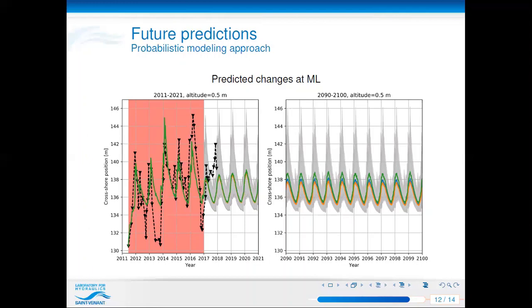so meters of variability. And the three wave projections differ only very slightly because the statistics and wave height distributions are very similar between those three projections. And so we see by the end of our time series, the equilibrium model predicts a very similar kind of constant shoreline change on average between the 200 different simulations, where we see no significant long-term trends.